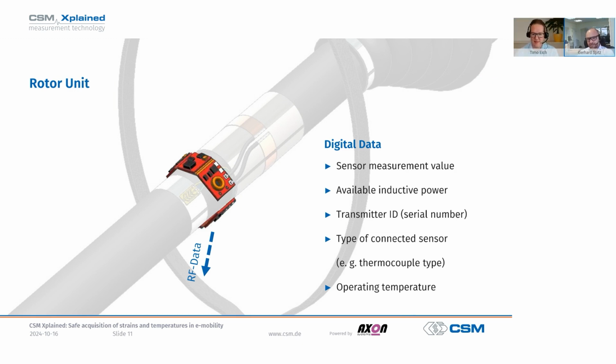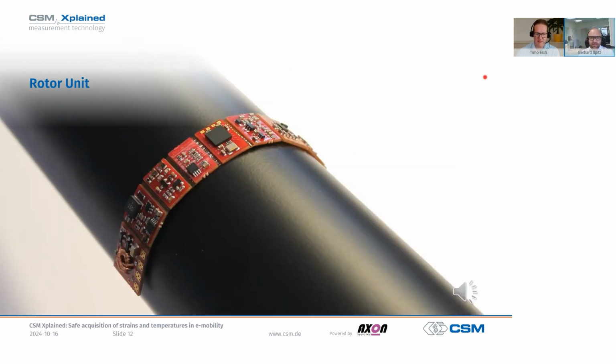Well, it depends. If we see a standard drive shaft, which is one of the most common applications, with a diameter of 3 to 4 centimeters at the highest and a speed of 3000 RPM, that is not really hard for imbalance. So you can just install the system with a flexible rotor unit, and that will be fine. If we have higher speed shafts, you can put a counterweight on the shaft, which can be provided, which is quite easy. Then you should be fine.